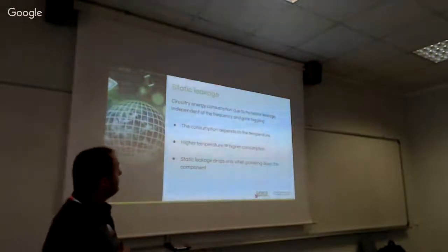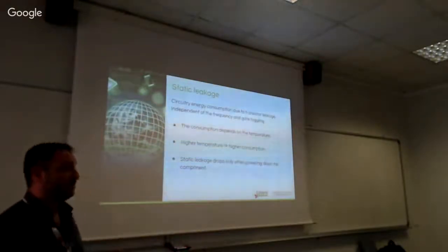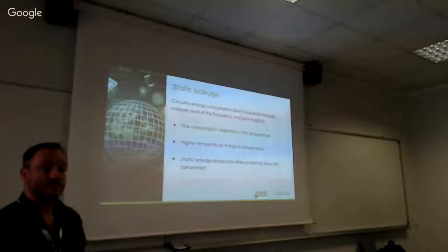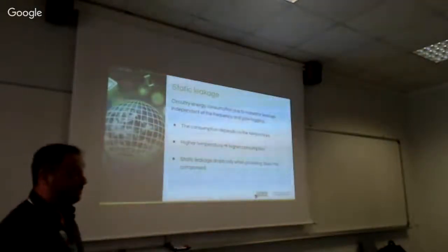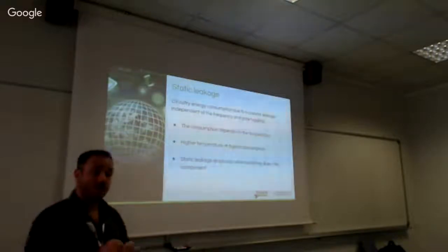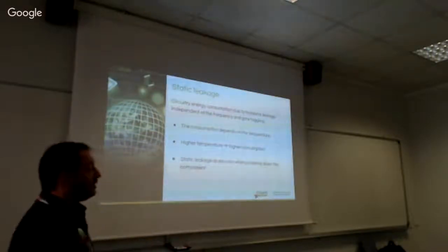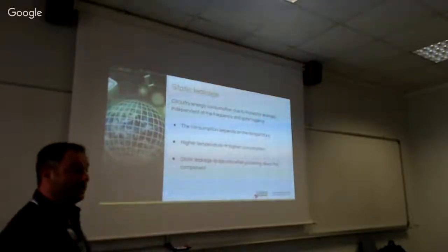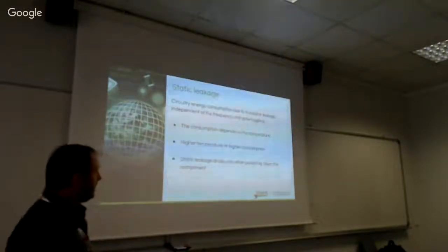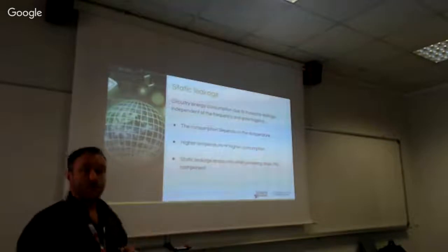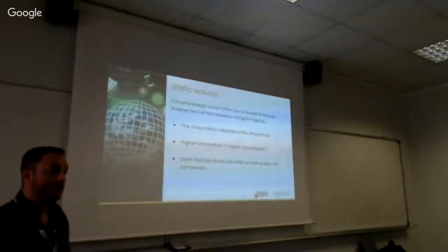The static leakage is the normal energy drained by the circuitry, not being used, but it's constant. It depends on temperature, so when the temperature increases, static leakage increases also. And the only way to drop the static leakage is to power down the component.